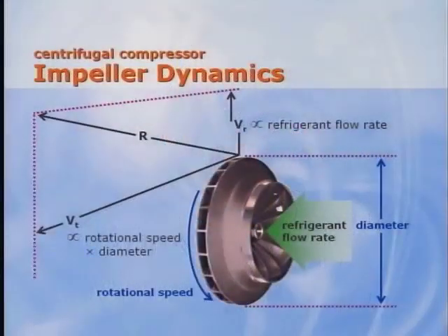The principle of dynamic compression is difficult for some people to understand. Why would refrigerant pressure simply increase due to velocity changing? Dynamic compression is similar to the static regain method used in duct design, where velocity pressure is converted to static pressure. Let's look at the velocity-pressure relationship that acts on the refrigerant vapor.